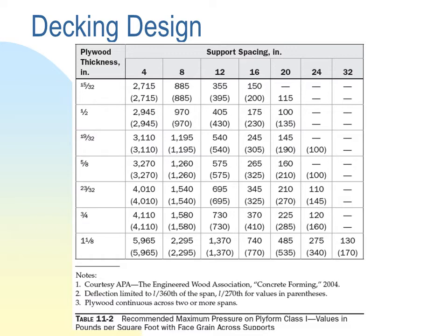So for what we call architectural concrete, you do not allow deflections in a slab that somebody could see. If somebody could see the floor above him, you should not allow apparent deflections within the beneath part of the concrete slab. People would not like that architecturally. However, for structural concrete, you could allow a little bit more. So if you have a full ceiling, you could allow larger values of deflection. The case of span over 270 is for structural concrete, and the case of span over 360 is for architectural concrete.